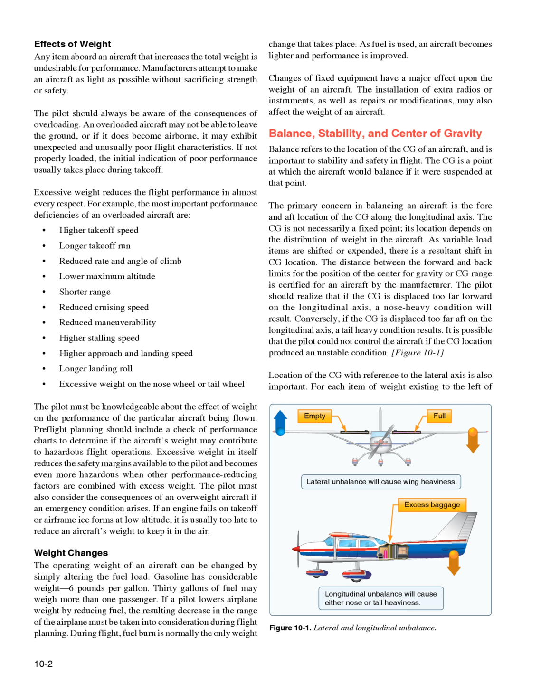The pilot must also consider the consequences of an overweight aircraft if an emergency condition arises. If an engine fails on takeoff or airframe ice forms at low altitude, it is usually too late to reduce an aircraft's weight to keep it in the air.